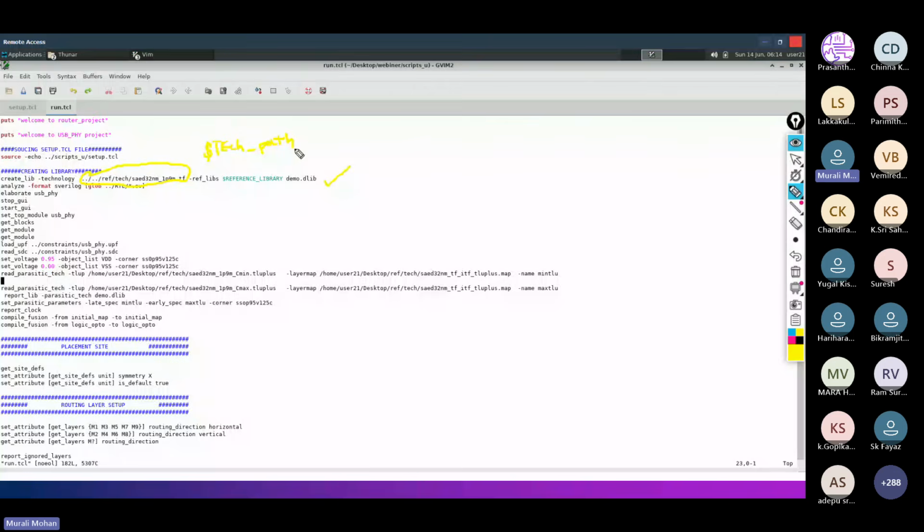Next is analyzing. Here we are going to use the .sv files, SystemVerilog files, and the command called analyze. In analyze, we verify the syntax of the particular logic. Verilog is also case sensitive. That is the way.